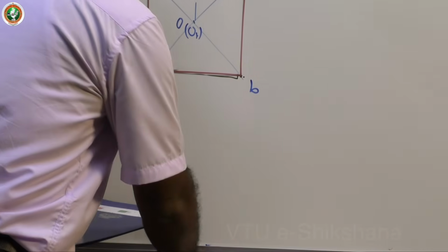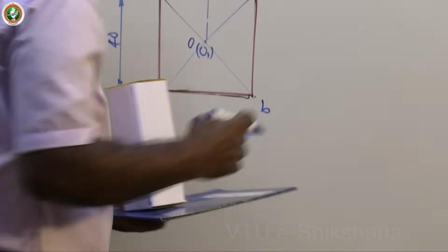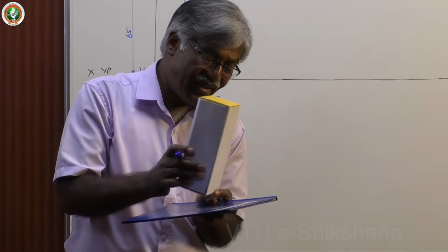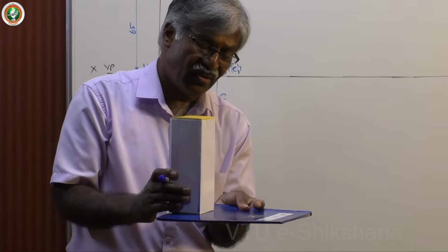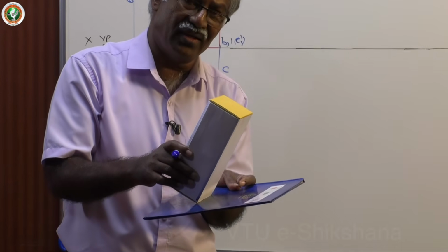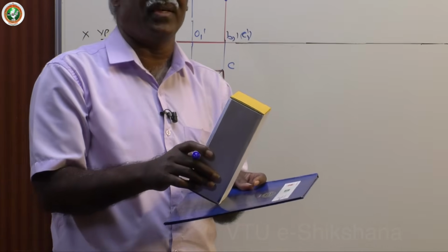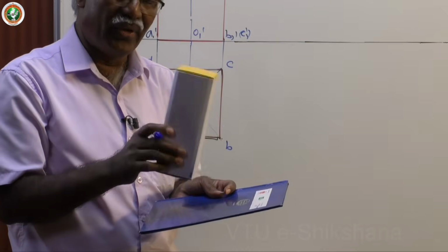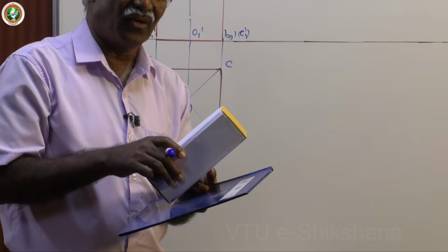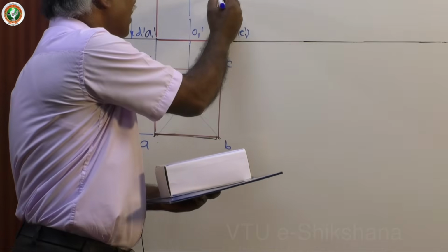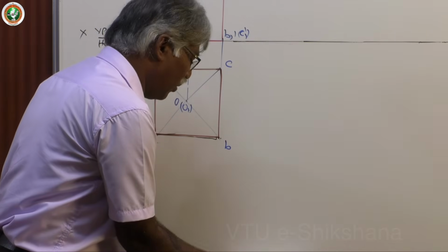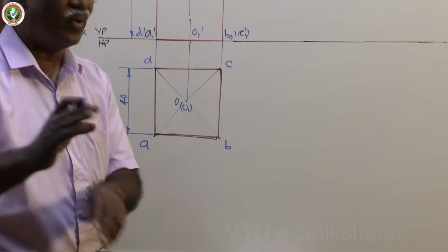This particular line is representing the rectangular face or lateral face containing the base edge on HP. This is inclined at 40 degree. The axis also assumes 40 degree. Instead of giving inclination to the axis to the HP, you take the reference rectangular surface and the corresponding line is this. You give inclination to that. Manually, you can do this way, and on a computer, you move and rotate 30.